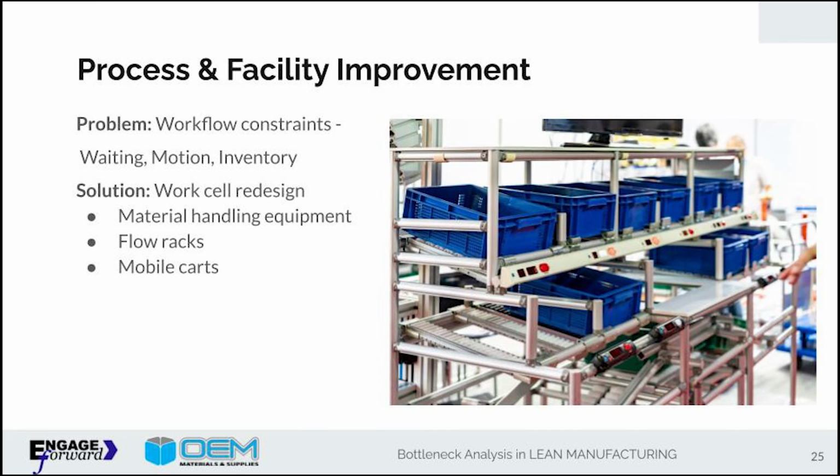One of the problems we've seen is that if the workstation is larger than the work being done, it starts to collect things like water bottles and purses and phones, things that don't belong on the work surface. So we want to limit the space of the work surface to just what is needed in that area. With ESD, you can't have anything within 12 inches that causes static. So the smaller the work surface, the better, so you don't collect unnecessary products on the station.